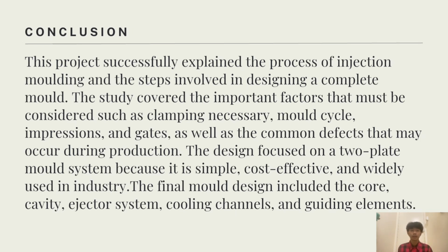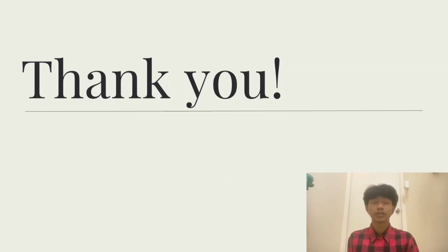The design focused on a two-plate mold system because it is simple, cost-effective, and widely used in industry. The final mold design included the core, cavity, ejector system, and cooling channel.